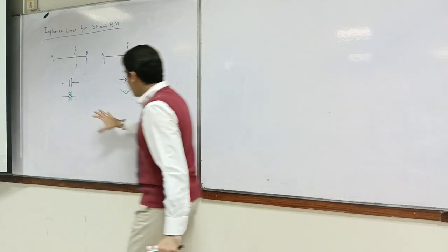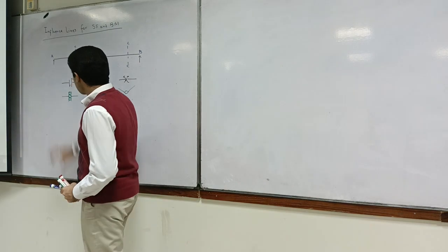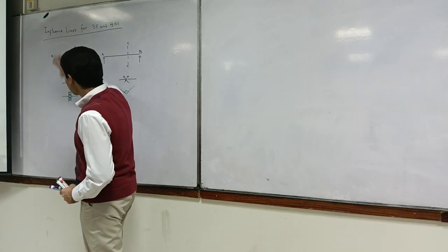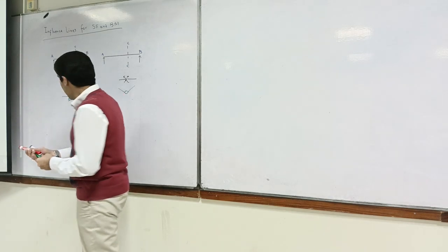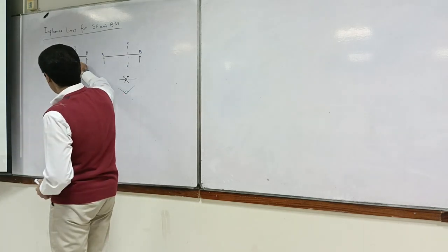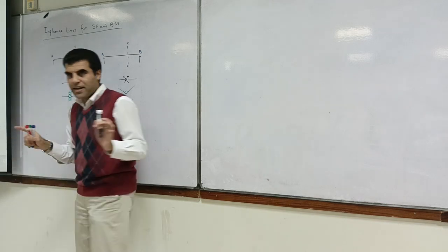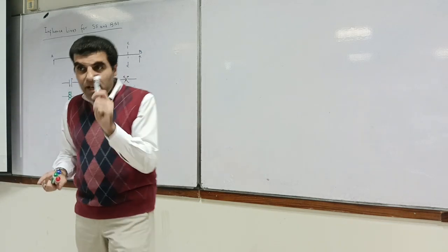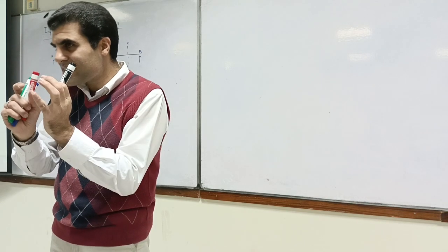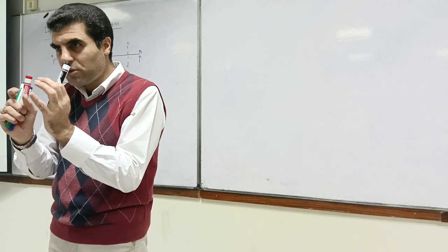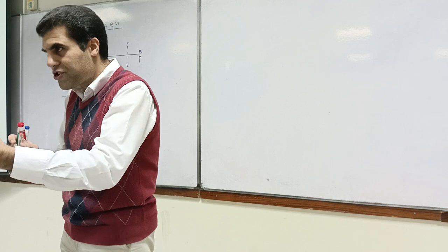Okay, so now this thing we will apply. Imagine we apply it over here. What will happen if you put it over here? Now you have got this thing, okay? What does the Muller-Breslau principle say? That you take that gadget, you release that particular action, which in our case is shear.